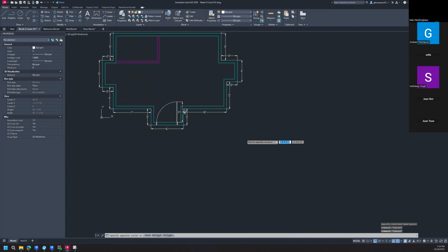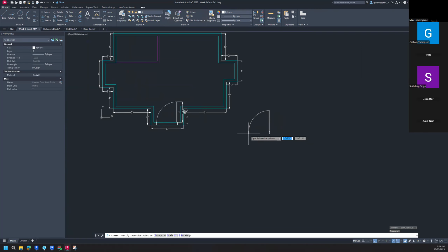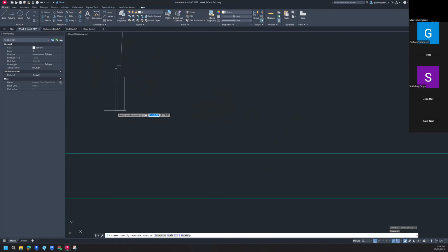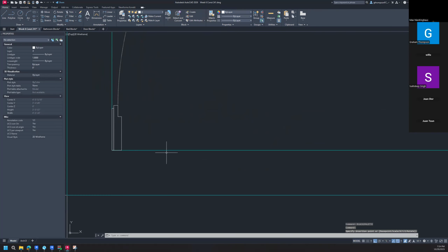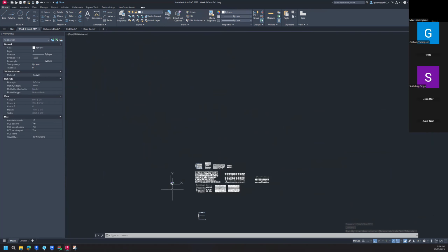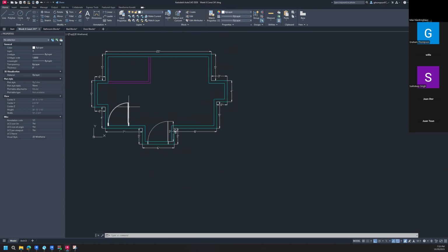So now if I went to the block palette real quick, and I know this is a little bit more than you're going to be doing all the time, but it's good to know. If I open up this blocks palette, here's this block now, and when I grab it and drag it over, you can see exactly where that block is going to place, right? If I didn't do that, it would just drag in and it would place somewhere randomly on the screen. So a little bit more advanced, I know, than you were looking for there on a block and how to use it. Okay, you wanted to know how to rotate a block.